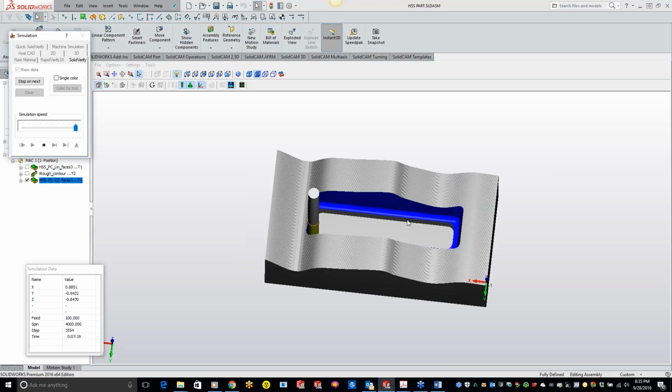Now we're still taking a pretty healthy cut here, so maybe I want to extend it out 6 passes, or obviously come in there with a rougher. In HSS there is some roughing options in there, but since we're working with Express here, we don't have a lot of options. So this is another way of just kind of getting around it just to get the job done, I guess you could say. And like I said, definitely not the most proficient, but we'll get it to work.